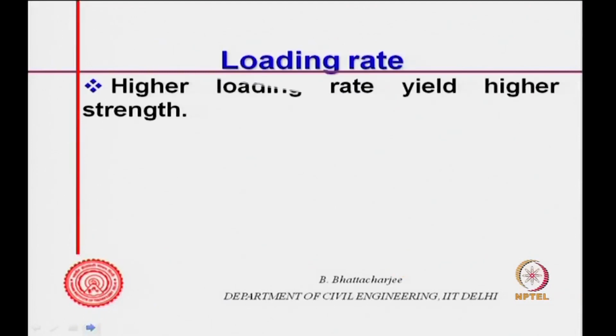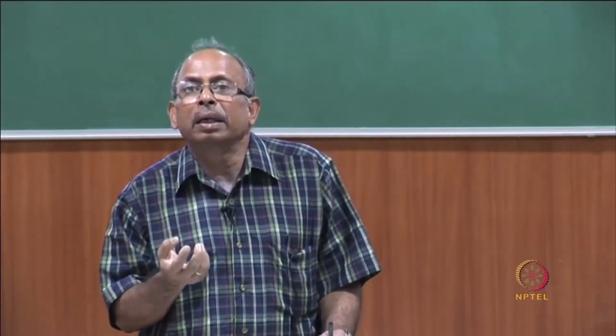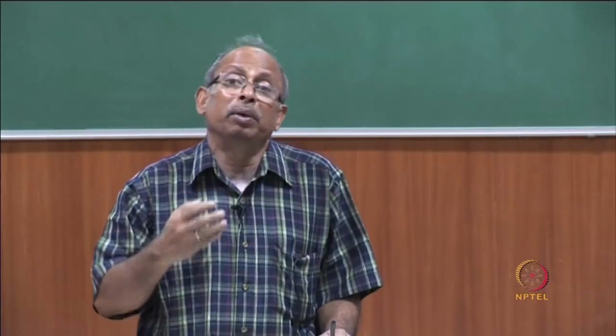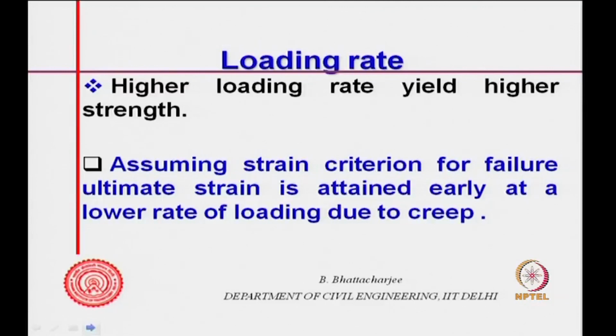Then the next important thing is the rate of loading. A higher loading rate yields higher strength. If you load it quickly, at a very fast pace, the fracture does not propagate so easily; it takes time. While if you put a sustained load, there will be the effect of creep in an extreme case, so some deformation might occur with time. So, if you are monotonically increasing the load at a very slow pace, the strength observed will be less compared to doing it at a fast rate. So, loading rate is also important, and many people seem to miss it.